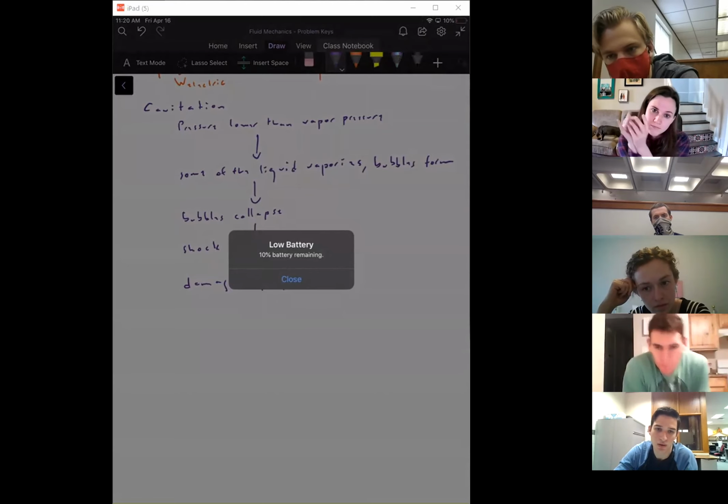Point 3, says Zach. Why? Because that's what the pump does. It adds pressure. We said that. Highest pressure in the pipeline. So after the pump, you get a really high pressure and it pushes the fluid through the rest of the pipe. Where will the lowest pressure in this pipeline be? Right before the pump.